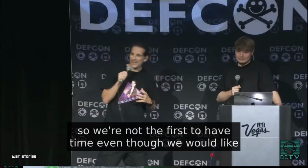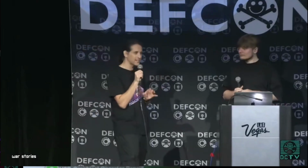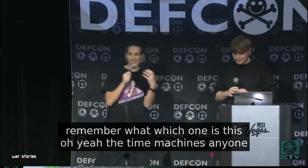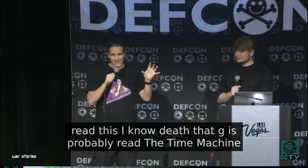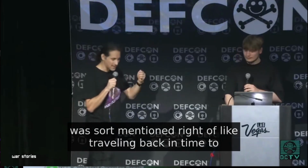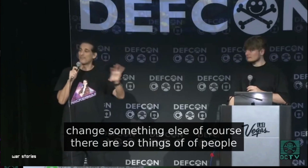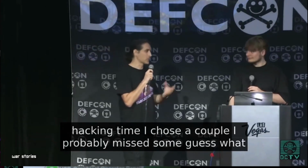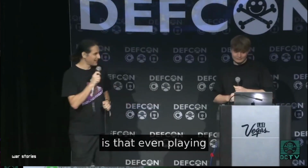It's called Nyquist's theorem. I need a sample rate of at least 800 kilohertz, how fast I'm listening to that data. And I can use a software-defined radio, but software-defined radios don't ever go that low. So the RTL-SDR, I'm not sure where that goes, maybe 100 megahertz, excuse me. The HackRF, amazing, I love the HackRF, but the minimum frequency it can listen to is about 1 megahertz, and we're at 400 kilohertz.